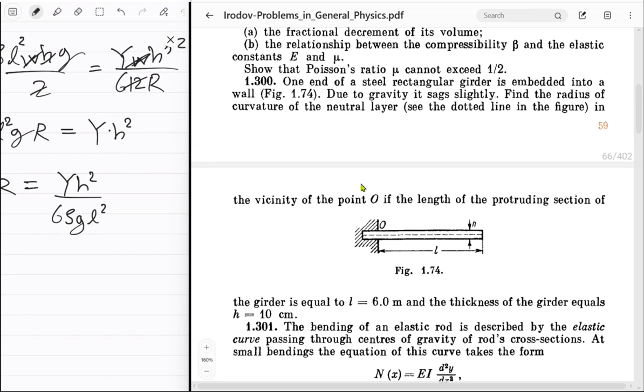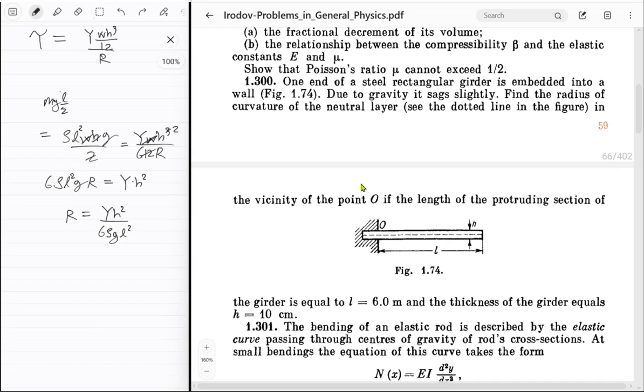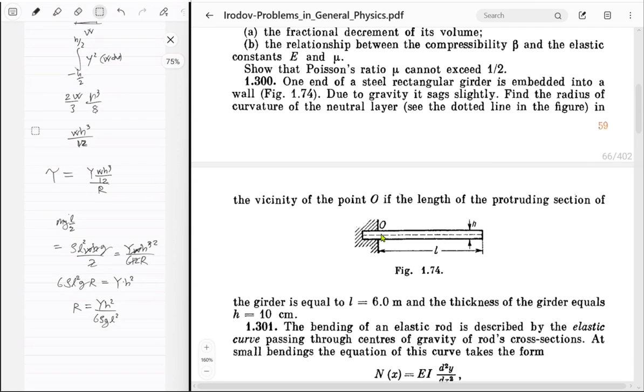So dimension analysis, this thing is like pressure times area, because Young's modulus is just units of stress, which is also like pressure. So pressure times area, just force. This thing is force. This thing is, wait, 6 rho G L would be pressure. Like it's just pressure times length. So pressure times length squared upon pressure times length. It's just length, right? So dimensionally, this looks correct. And I think that is in fact our answer, right? So you got the radius of curvature at x equal to 0. Cool. So that's our answer. Next question.